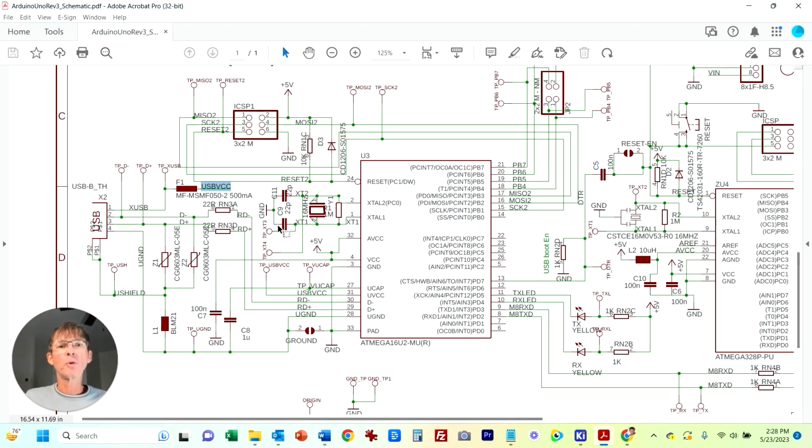Everything in a microcontroller or microprocessor, in the world of digital, almost always has a clock that everything synchronizes to. The faster this clock, the faster data is typically processed by that microcontroller. This is only 16 megahertz, which is pretty low end even for a microcontroller. For microprocessors, like in your phone or your computer, this would be 2, 3, 4 gigahertz, so 1,000 megahertz. So much faster than only 16 megahertz.